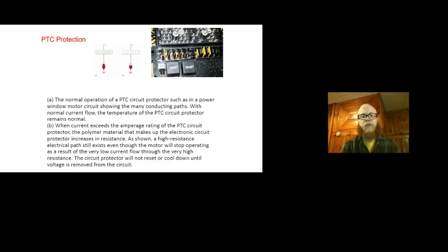But say something goes wrong with the circuit, they add this PTC protection, which stands for positive temperature coefficient. And what that means is as the temperature of this device goes up, and this is a semiconductor, so does the resistance, which then limits how much current can flow through the circuit.